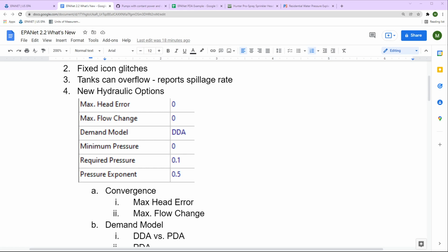And I believe they've put these additional criteria in here as a way to reduce the jumping around of the numerical results around these types of nodes and links in EPANet, such as valves that tend to bounce around because of the status checking in the EPANet engine.